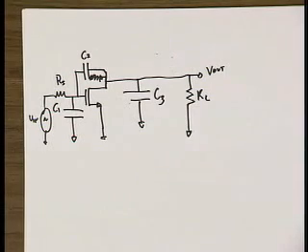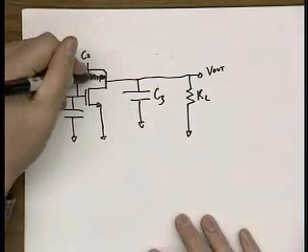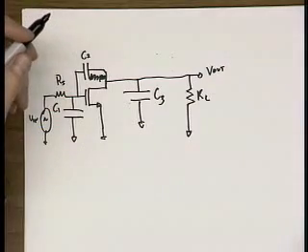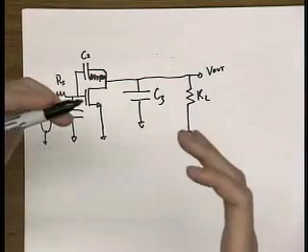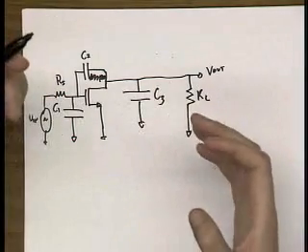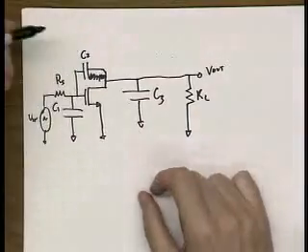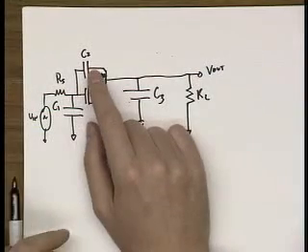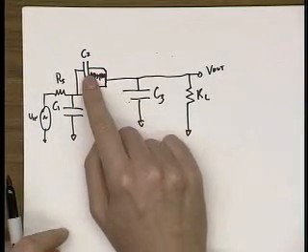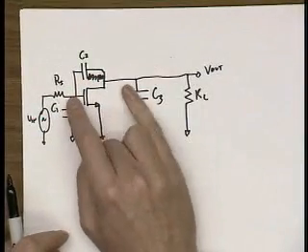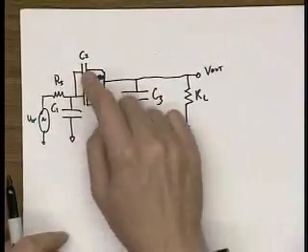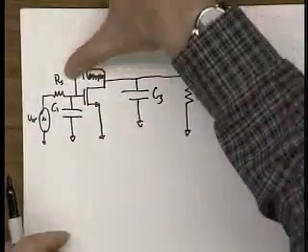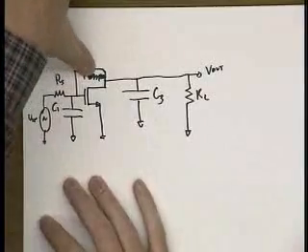So now let's think about what the poles are. The poles interact, okay? The way you can understand that things are interacting is that the input and output interact because of this C2 branch. This capacitor directly couples the input and the output nodes. If C2 were equal to 0, then calculating the two poles would be trivial.